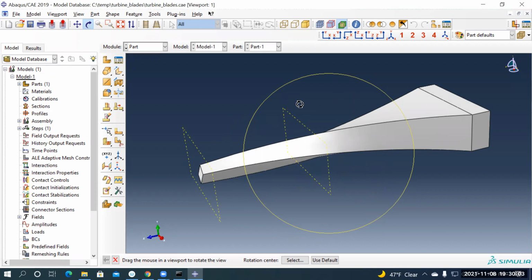Anyone had any trouble? I'll come and help you out. Quinn, was it able to do loft? Yeah. You have still the same problem? Yeah. Like you said, you forgot to select one more here. You can use this one. So go back to, yes, section 1. Yeah, now it will do it. Okay. So it can't be an open section, so make sure you're selecting all the 4 edges of the rectangle. Anyone had any trouble?